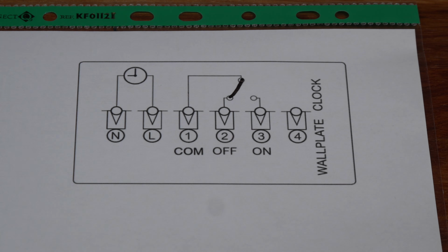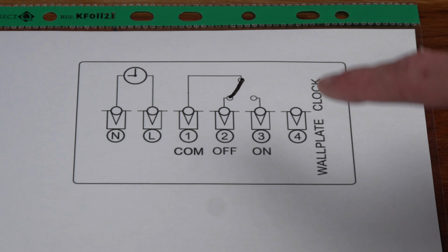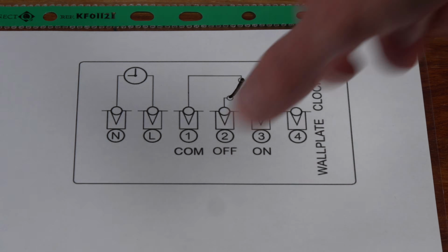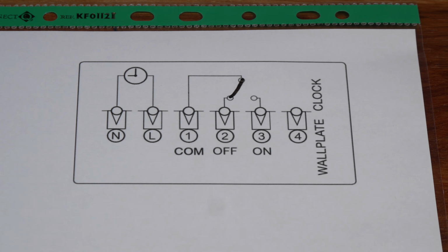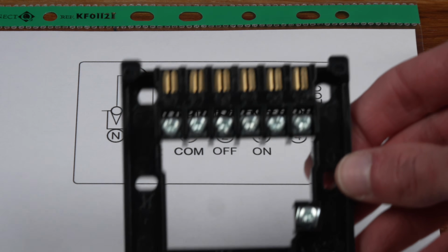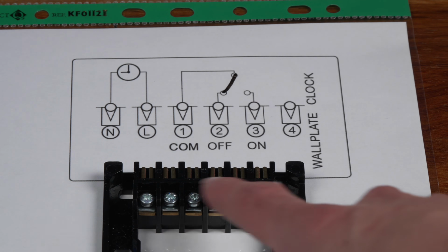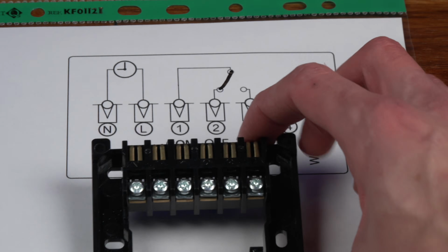So first up, here we have the wiring diagram for the single channel hub, and this is what you'd use for a combi boiler with a single heating zone. This is the sort of diagram we'll take a look at here. This is out of the manual. Each of these terminals relates to one of these on the hub itself. So if you put that there, you can see these are all labelled with numbers, and the numbers reflect what we're going to see on the diagram here.